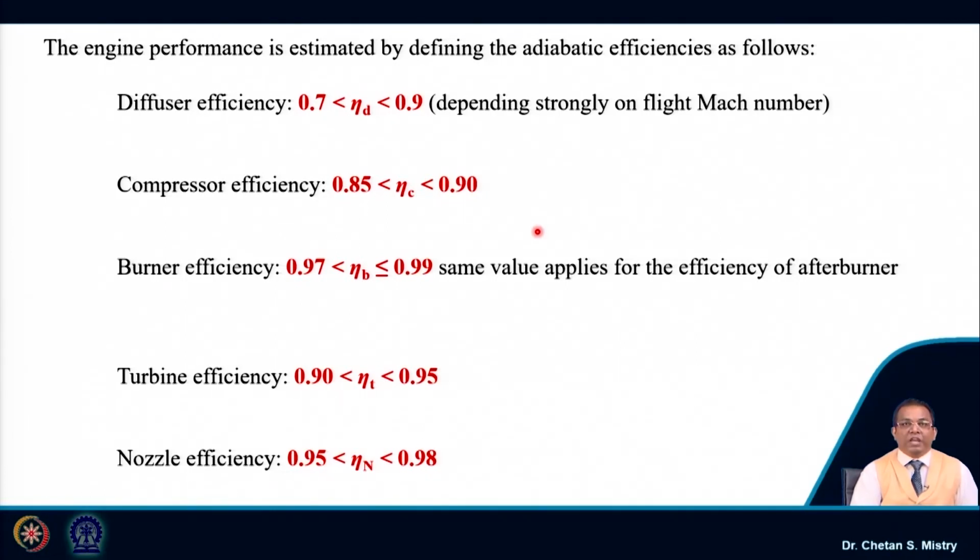Just realize one thing: when we are starting with the initial, very first step of the design for a gas turbine engine, we do not have this information available. So, we need to assume these efficiencies. The very first step, we will be assuming the efficiency, based on that we will be doing all our calculation, and from that we will try to assess the performance. Based on that, as we have discussed in our first week, we will be going through a number of iterations in terms of cycle analysis to meet the